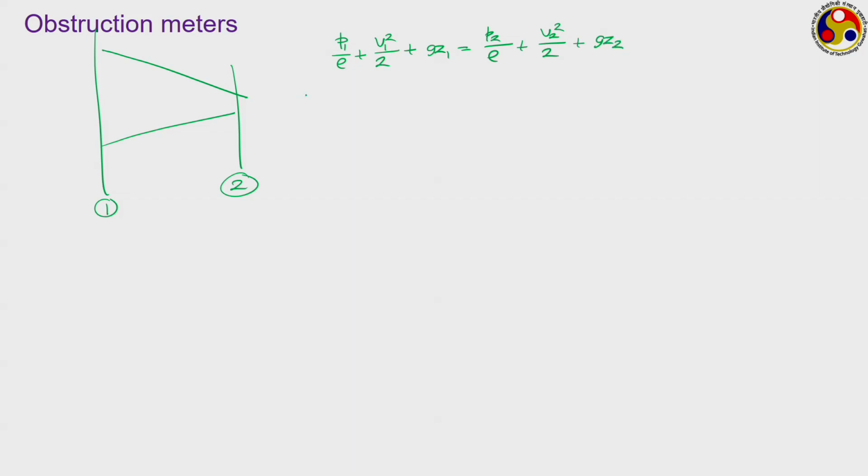And if there are any frictional losses, quite often we add hf, which is a loss of pressure head in a way, sometimes not truly pressure head. We can add a g hf term, where hf refers to a pressure loss head or some kind of loss coefficient, but here we are not going to talk about this for now at least.